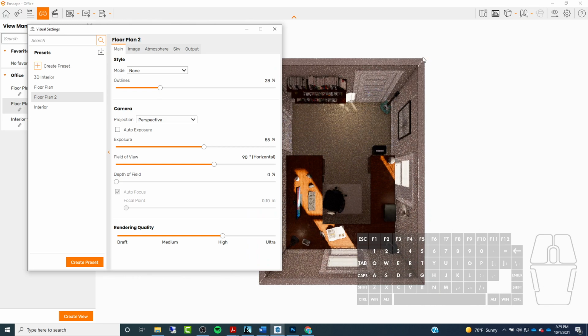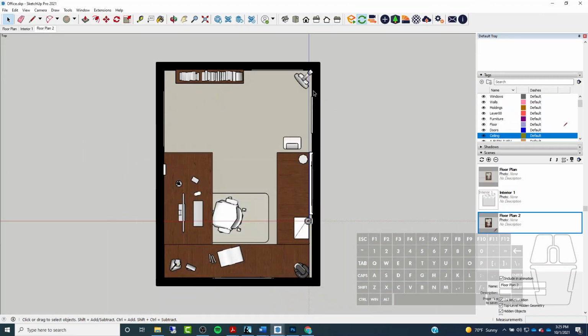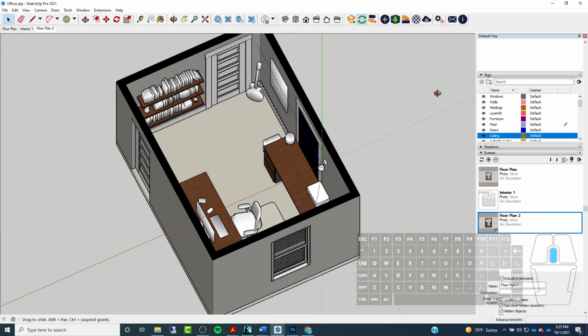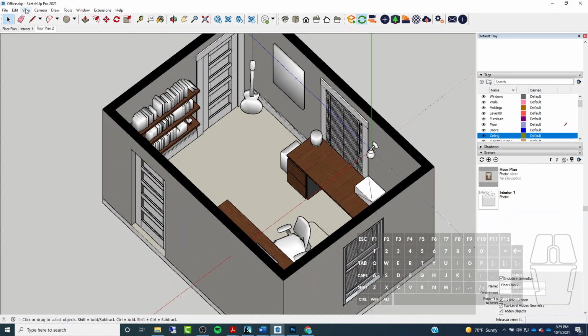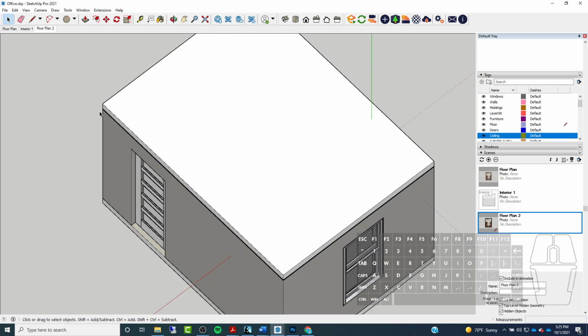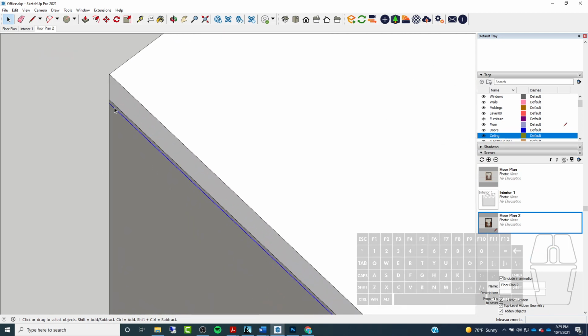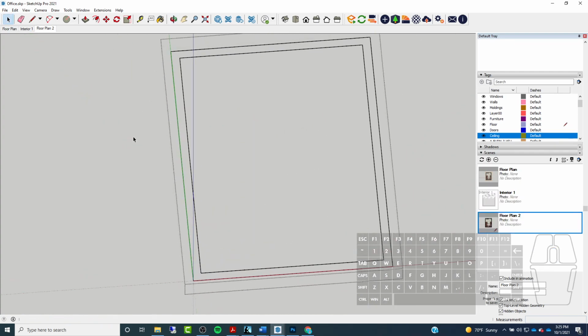So now what I want to do is add in sort of my poche to fill in those walls. So this is where that cutout, or not cutout, that group from slice that I did earlier comes in. So if I go here really quickly and let me turn off my live updates, go to view and then hide my section cuts. I'm going to find that group that I made the cutout of, and then go in here and I'm going to fill this in with some geometry.